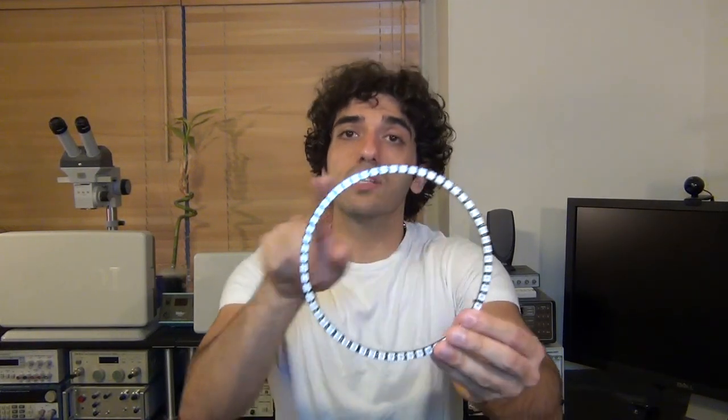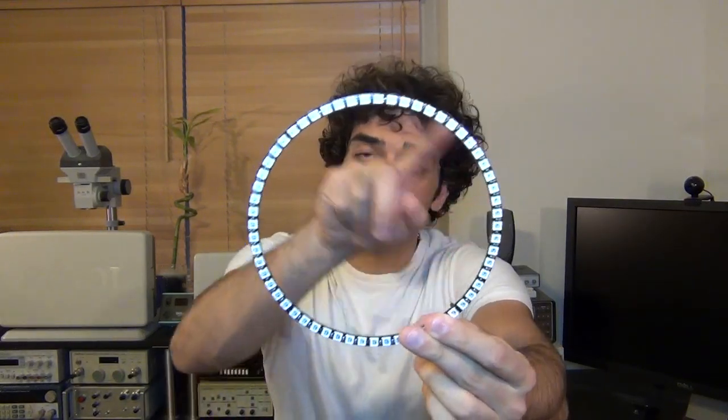So these little LEDs are one-wire addressable 24-bit color LEDs, so they're really powerful. You can create a whole bunch of interesting patterns, program them to have all unique 24-bit colors, and every internal protocol is already taken care of, so it does PWM internally. You don't have to worry about any of that. And because they use one-wire communication, they're essentially cascaded, so you can have many of them in a row and just program them all in a serial fashion and then turn them all on at the end when you're done.